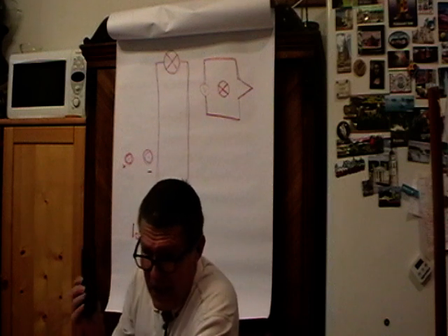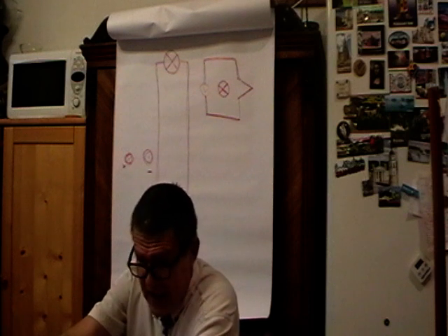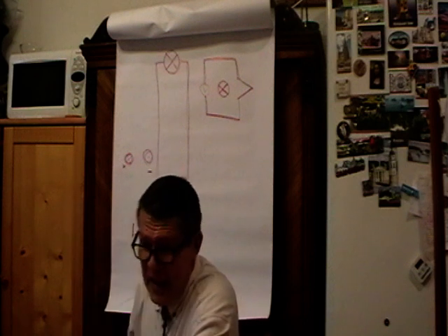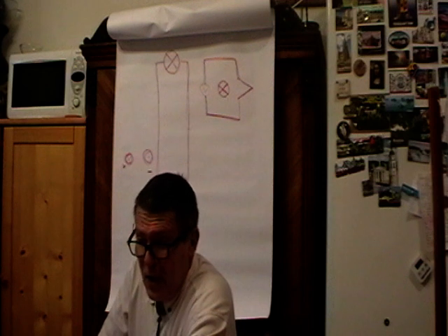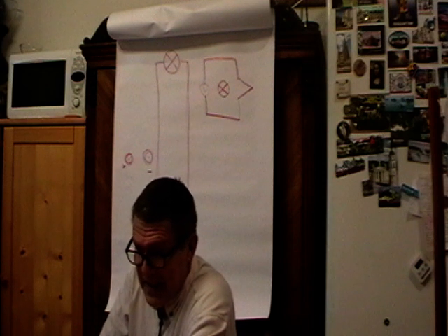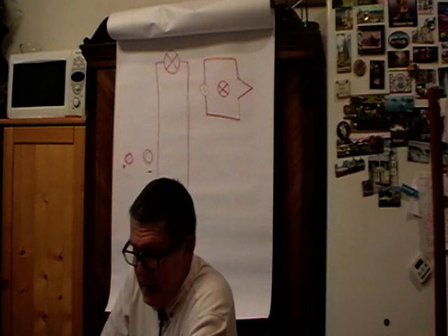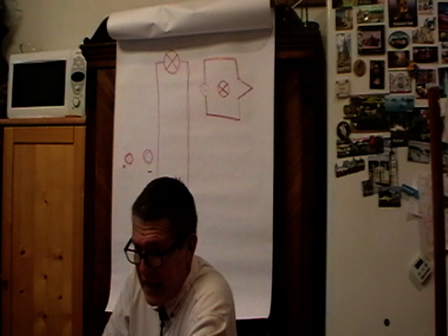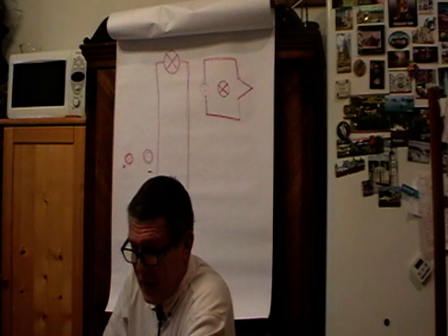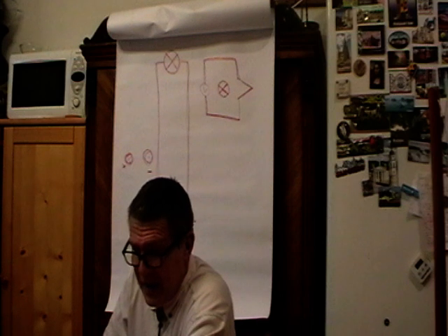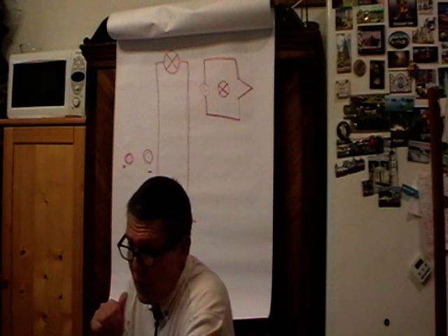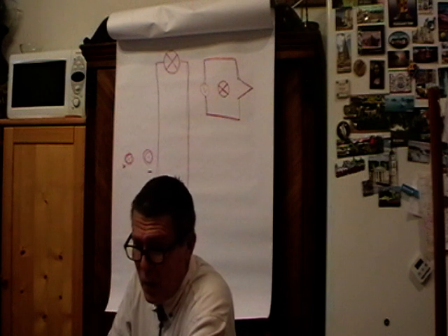So applications like mobile phones, telecommunications, and microwave ovens are those that cause us to consider also wave effects. But the important point is that we have a time delay that is incurred by the signal when propagating through that transmission line or media. And this gets important once the dimension of that line gets big enough to be comparable with the wavelength. And the rule of thumb is 1/12 of the wavelength.